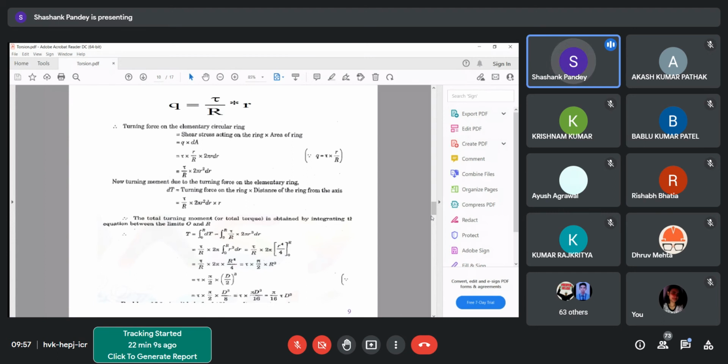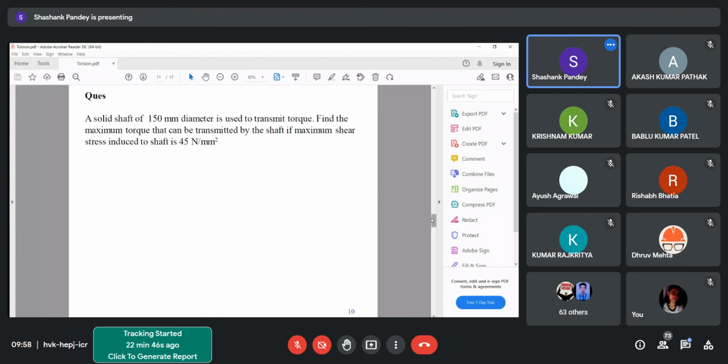So why don't you give me the expression for T for the hollow circular shaft? If you have said this correctly, the limits are going to be changed. So let us see. In the initial expression, D cube is replaced by D to the 4 minus small d to the 4, divided by D. Correct, absolutely correct. So the initial expression becomes pi by 16 tau into (D^4 minus d^4) upon D. Okay, can you quickly give the answer for this question?